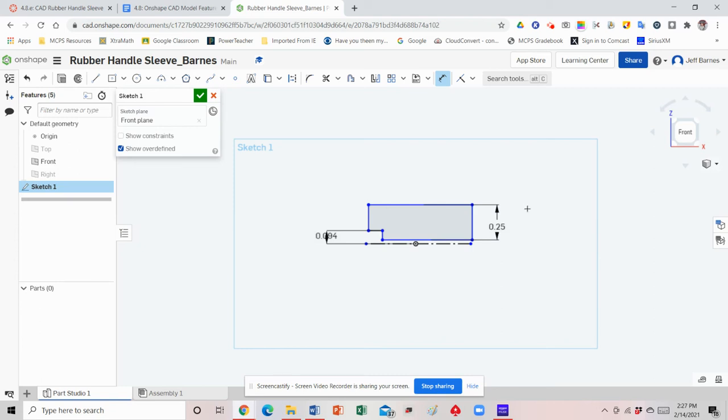Okay, so notice it dropped my figure down pretty low here. If it does that, usually what I can do is turn off the dimension tool and just grab that line, that edge, and it'll slide. You can then just left click and hold and drag it up, and it reforms the shape that I want. But it's keeping the correct distance.